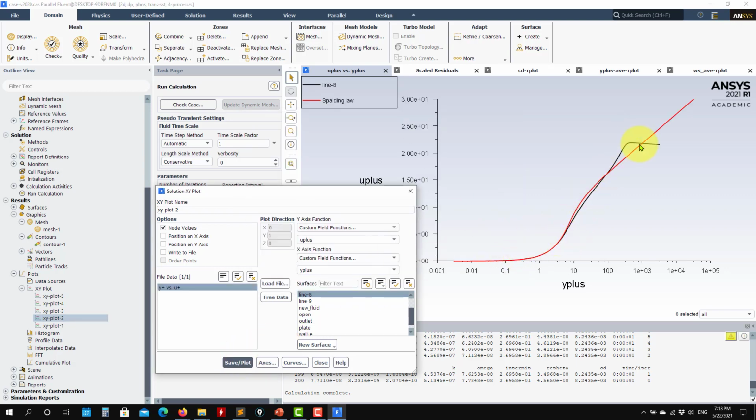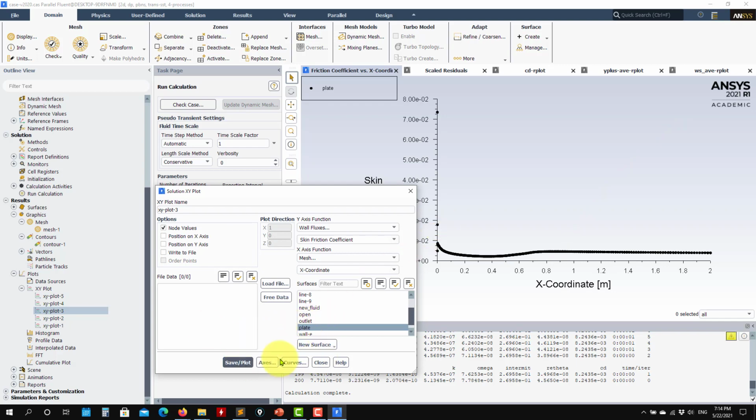Okay, so see that comparing with the Spalding profile, we have quite good agreement there. It's not to say that the Spalding profile is the good one, but between these two, we have a large deviation in the buffer region. That's why we avoid it, because in that buffer region there is not a universal or good enough fit. So all the models will have the largest differences here. And this small deviation can account for 10, 20% of error that you are going to carry into your turbulent region.